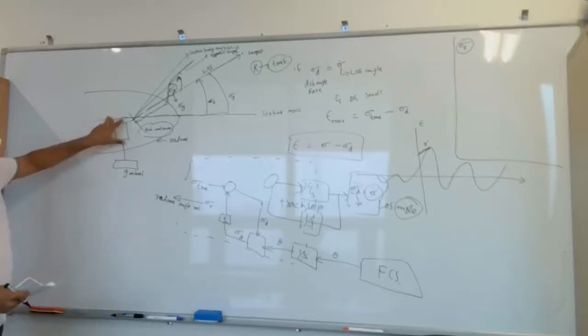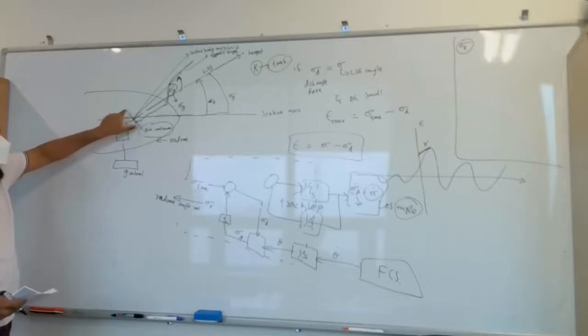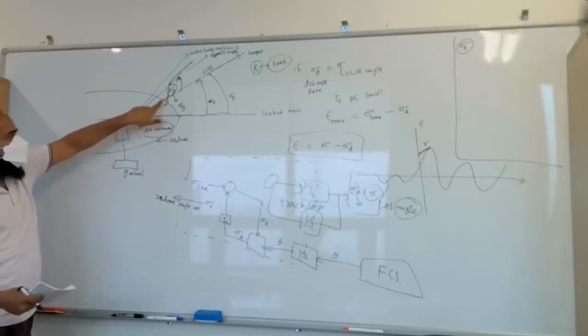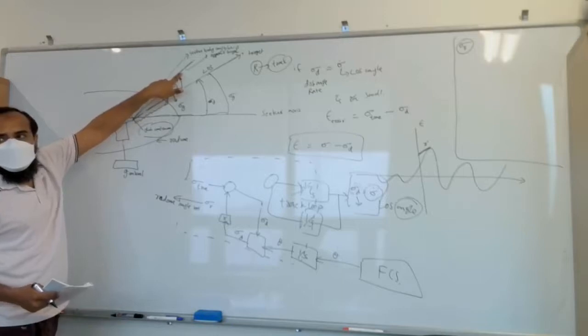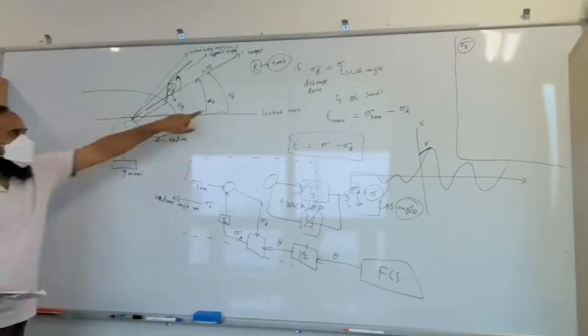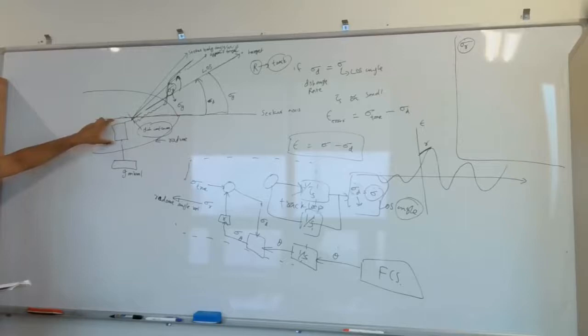Okay, but the gimbal is positioned like this one, and the antenna position is like this one. If it is at this position, then due to refraction the signal goes upward here. So our FCS control system monitors the center axis of the seeker to reconstruct the line of sight angle by moving the gimbal angle here and here, so that it makes the exact line of sight range here.